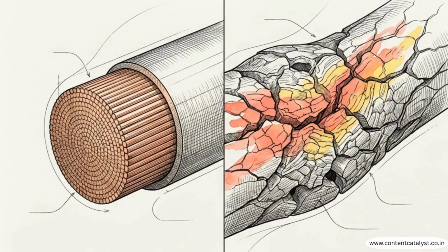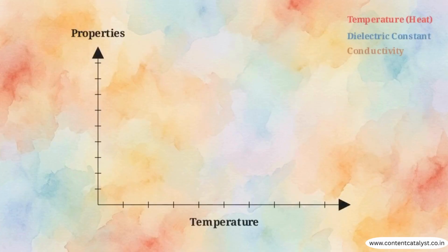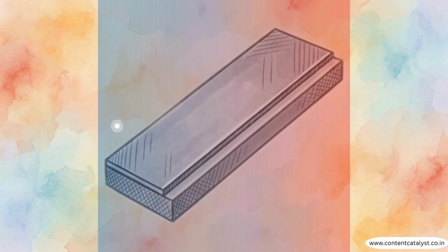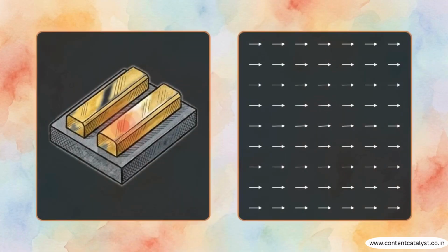This heat alters the physical properties of the materials. As temperature rises, a material's dielectric constant and electrical conductivity shift. This top-down view shows a circuit trace beneath a thermal gradient. As the signal encounters hot zones, it warps the electromagnetic behavior, scattering the signal flow. CST Studio Suite solves this by using tightly coupled multi-physics simulations, analyzing both thermal and electromagnetic effects simultaneously.